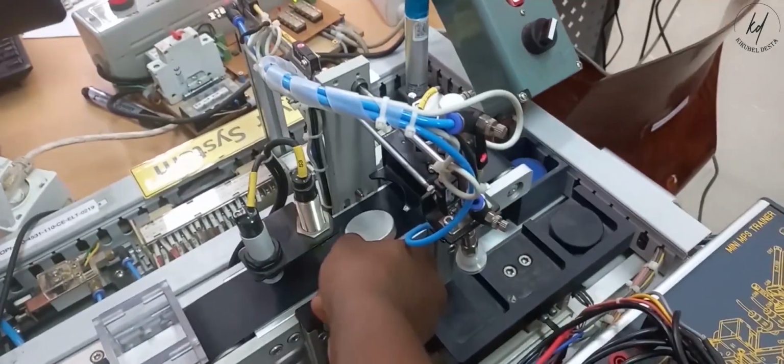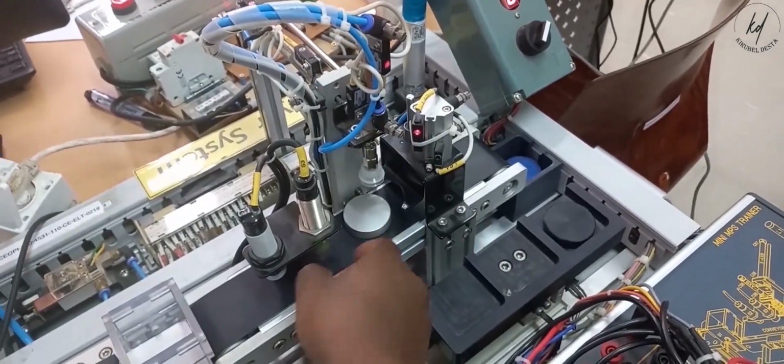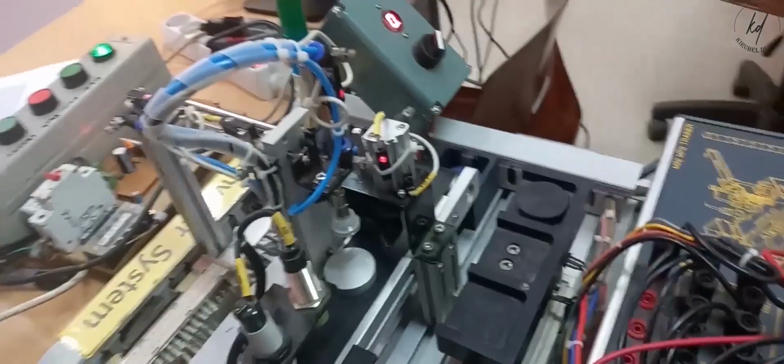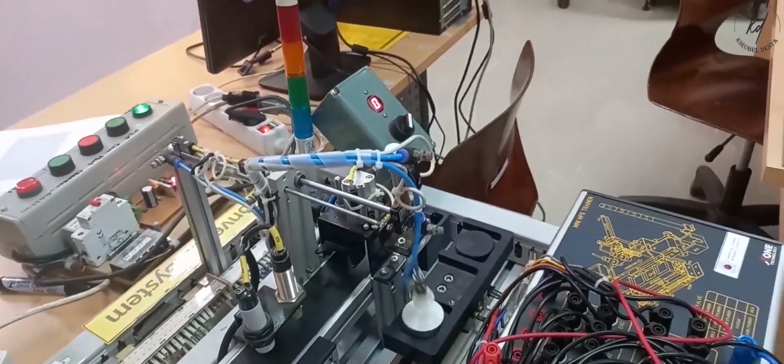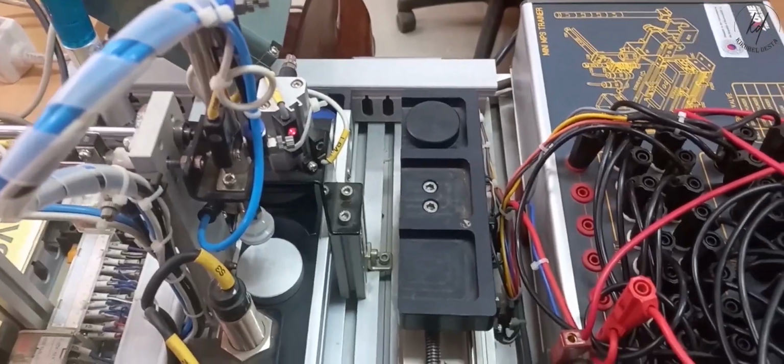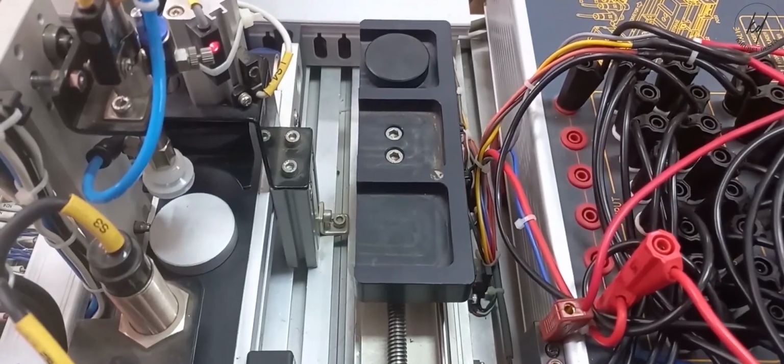As the push button is pressed, the Z-axis cylinder goes downward and vacuum suction turns on and picks an object in front of sensor 4 that is called back_det. Then, holding the object, it raises back, that means the Z-axis cylinder uplifts.